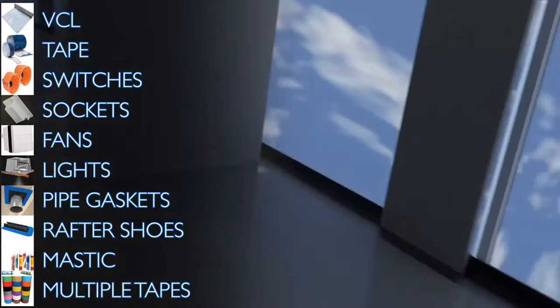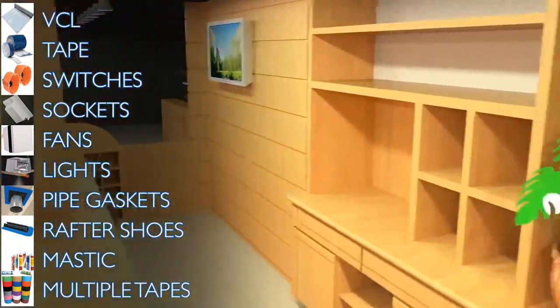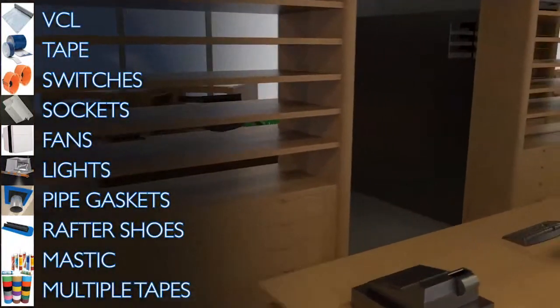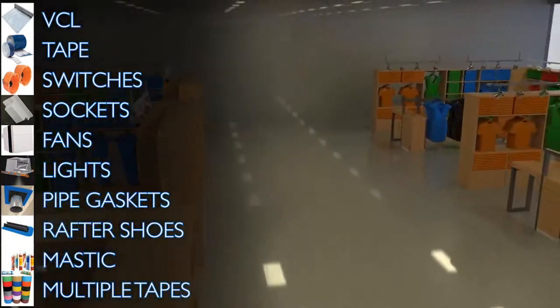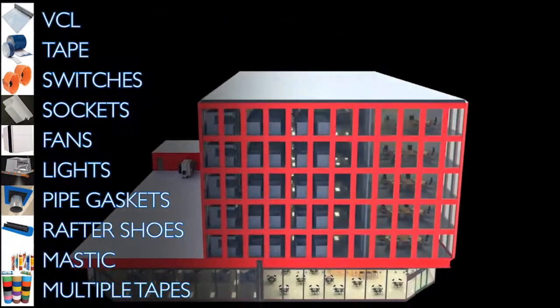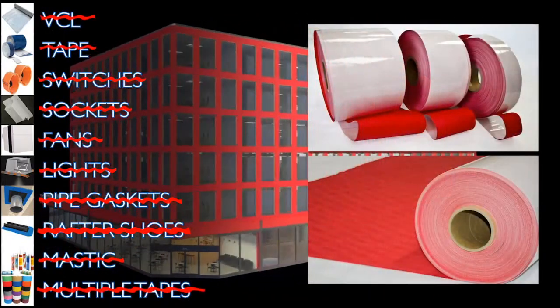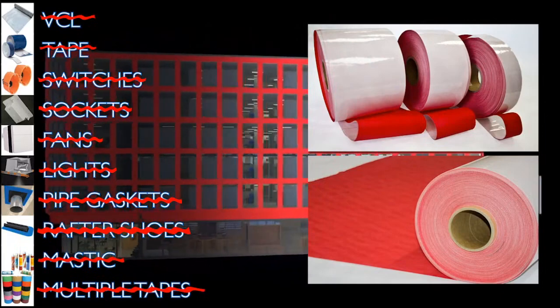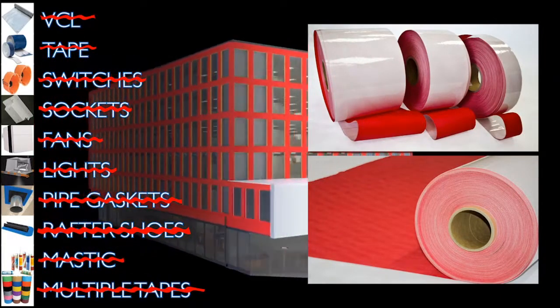These airtight accessories are generally more expensive compared to standard non-airtight versions and take more time, care, and attention to install correctly. There can also be supply chain issues acquiring these products at short notice. In contrast, external systems generally require far fewer components and do not require as complex an installation process, leading to faster completion of the airtight envelope with fewer potential delays and construction errors.